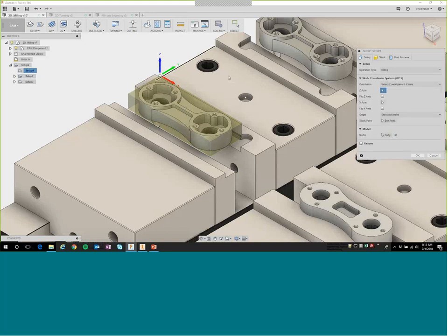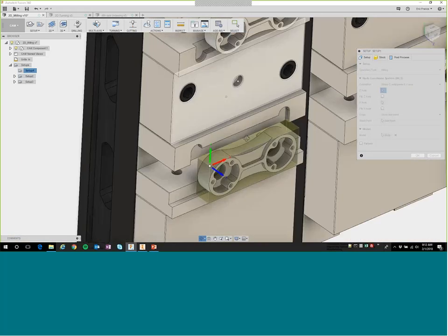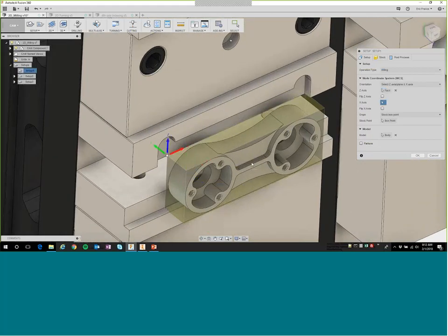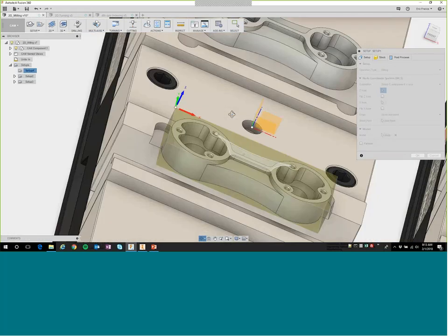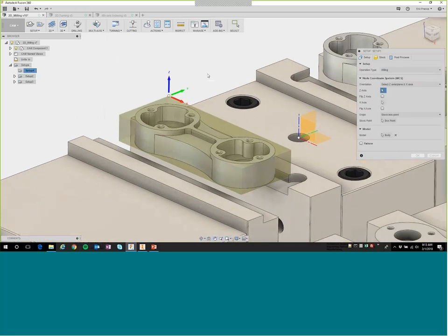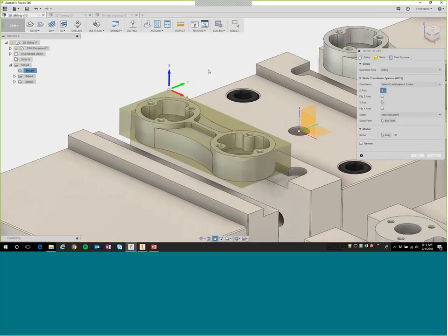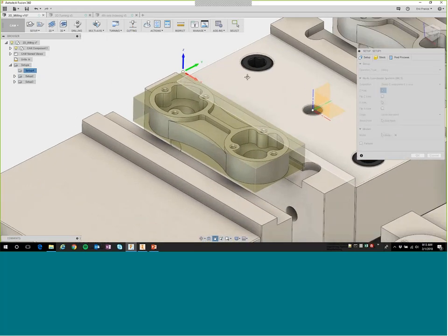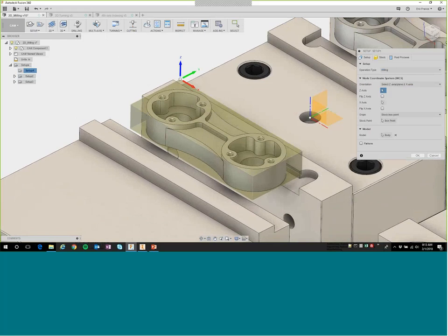Another nice option is if I happen to be doing some tombstone machining and actually need to reorient my Z-axis, I have the ability to go in and just pick a face I want to be normal to, and it'll adjust those automatically, right? And if I don't need to do that, or need to flip that around, it's just a matter of making a different selection again to get back to that stock box point. So some nice functionality just with setting up our work coordinate system and identifying where that origin needs to be.